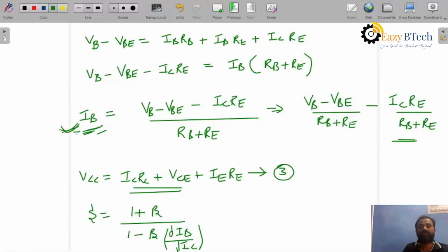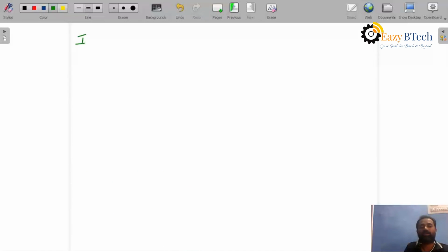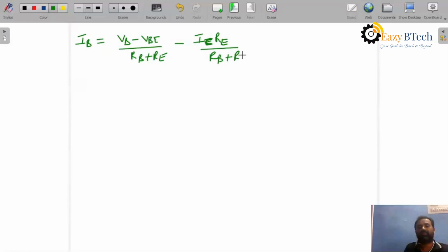Now students, you can see we got IB as VB minus VBE by RB plus RE, minus IC RE by RB plus RE.